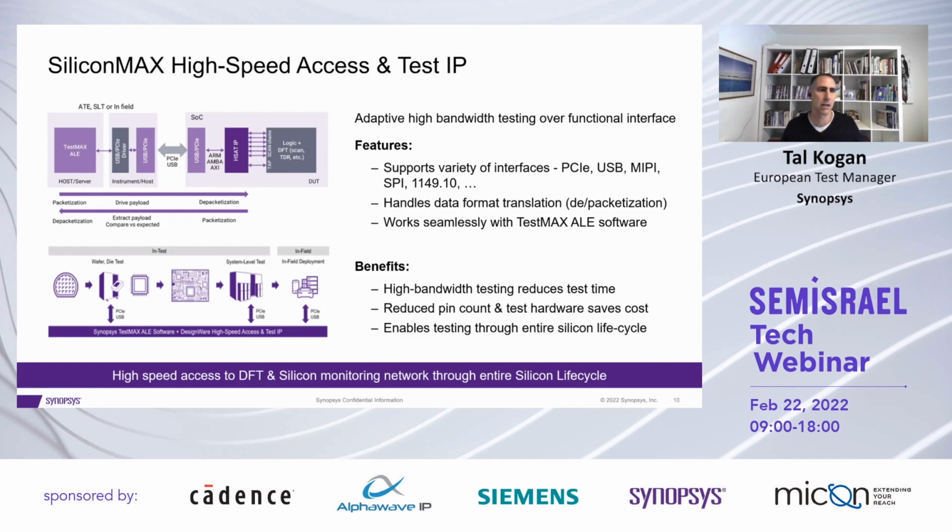Again, let's assume you have your tester here, and through that, you drive the functional interfaces of your USB or PCIe into the SoC, and data is written through your AXI bus into the IP, which actually translates that into scan data, driving at the end those internal scan chains that you still have, right?